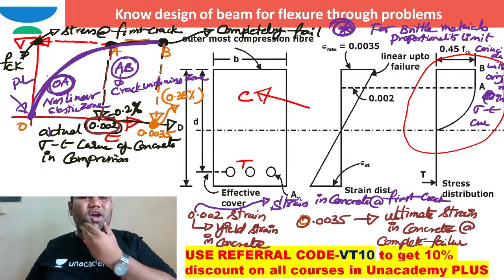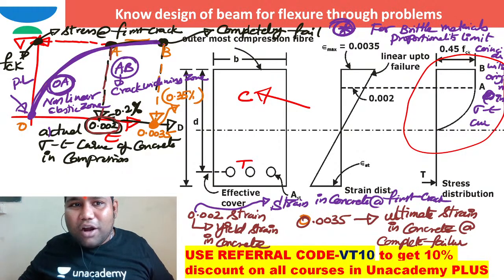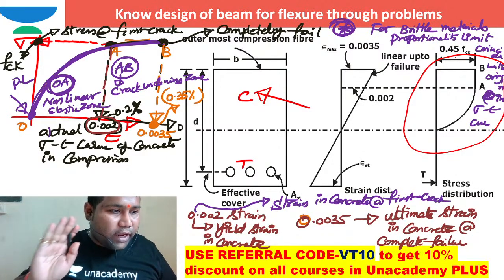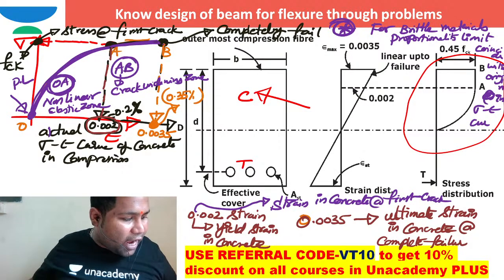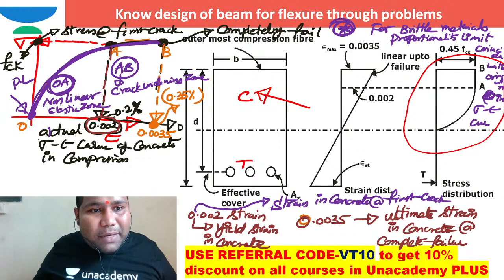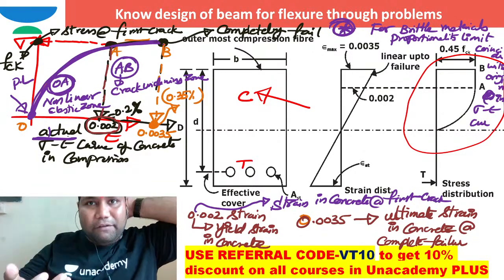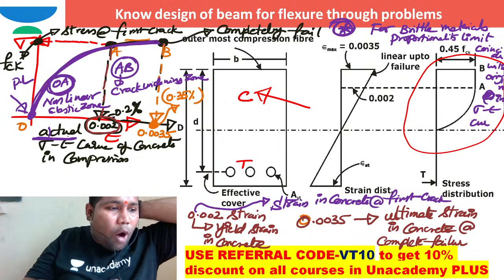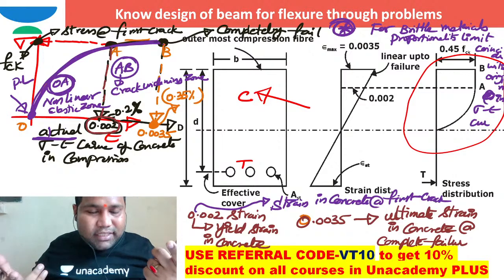Okay, now this is the actual stress strain curve. But now the question is, sir, why does this curve have this shape, and why am I getting this 0.45 of secant? Let me come to that. Please understand, this is the actual stress strain curve. But in order to make our analysis simple, I need to idealize and simplify this stress strain curve of concrete in compression.